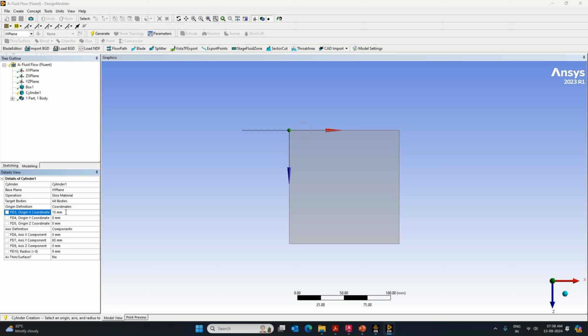Now similar to this, we have one more layer, but the distance here is 22. So this was 28.5, now the distance here is 22. So accordingly we'll proceed. Create one more time. You have to go with the primitive, that is cylinder. Instead of add metal, make it slice metal. X component we will take as 15 plus the horizontal distance between the cells. So this is 22. So 15 plus 22 is equal to 37. So the x component now will be equal to 37.